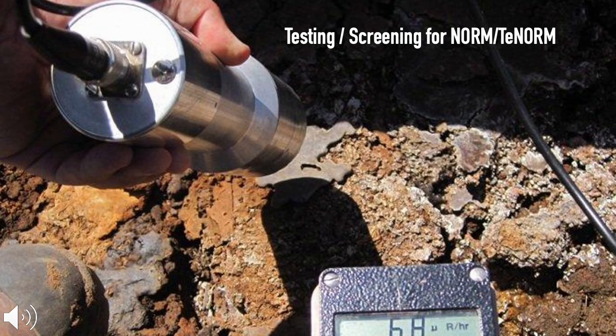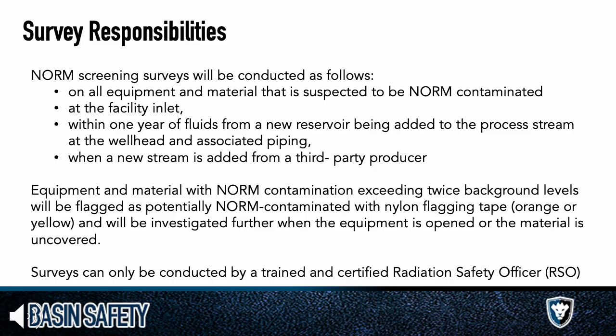Now we'll get into the testing or screening for NORM or TENORM. So we have some survey responsibilities. NORM screening surveys will be conducted as follows: on all equipment and material that is suspected to be NORM contaminated, at the facility inlet, within 1 year of fluids from a new reservoir being added to the process stream at the wellhead and associated piping, and when a new stream is added from a third-party producer.